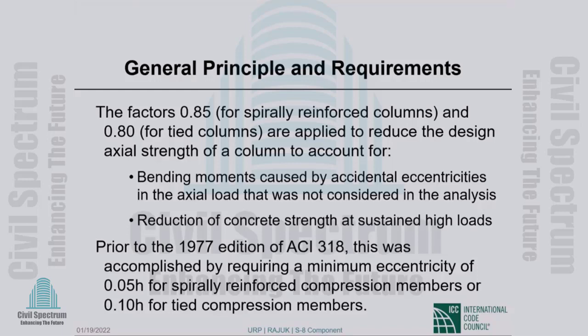So under sustained loading, you find lower strength compared to what you would find under what is considered to be a normal rate of load application. Okay, but that is not a huge amount. I do not know that is the reason for 0.85 or 0.75. That's not a big reason. The big reason is this accidental eccentricity.